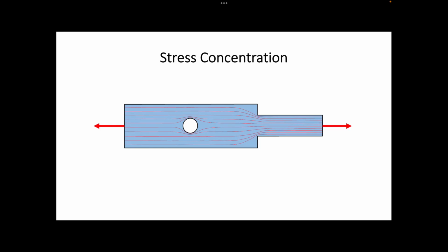To explain, the red lines that we are seeing are the trail of the water droplets, the red dots that we saw in the animation. They are called force lines in solid mechanics. Since we know the stress is the amount of force exerted per unit area, the location where the force lines are dense or very close to each other should indicate stress concentration.